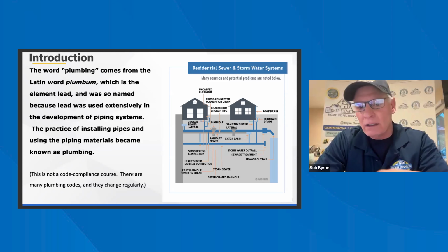Dishwasher, these are some of the requirements, not that we're doing anything from a code standpoint, but Jim mentioned the high drip loop, which is important. Some states require the air gap because you don't want the dishwasher to get wastewater from the trap down below. If you look at this illustration, you have the trap down here.